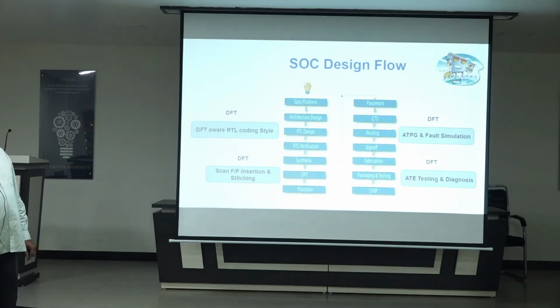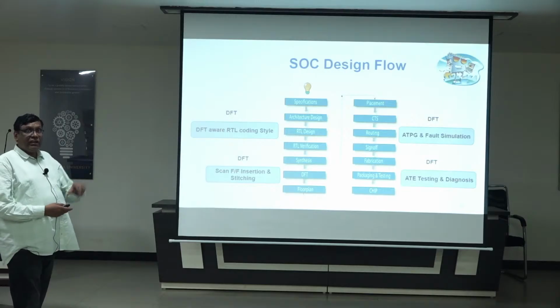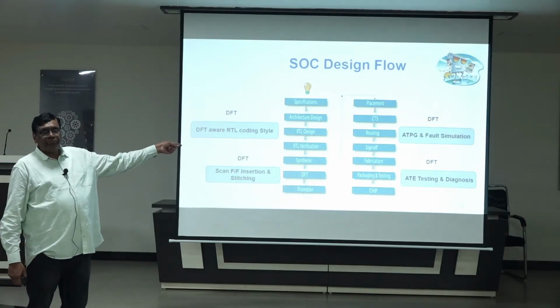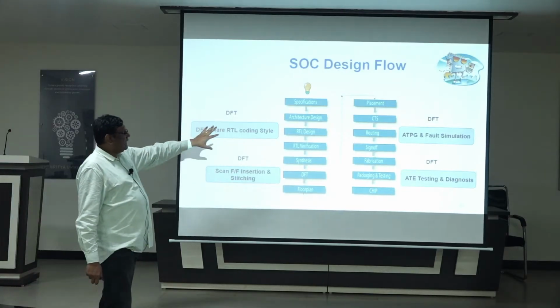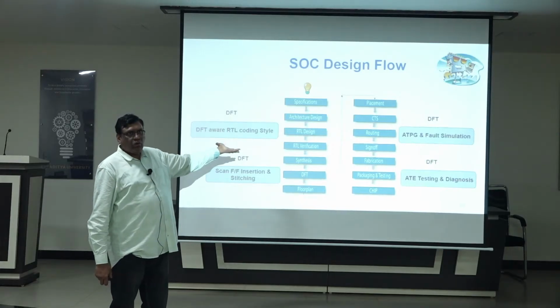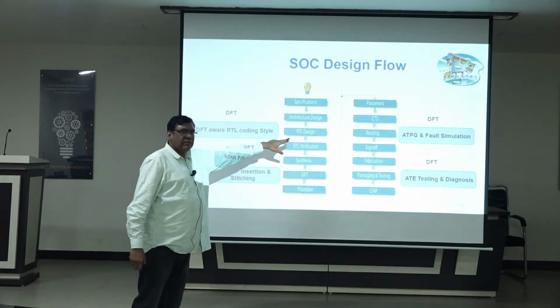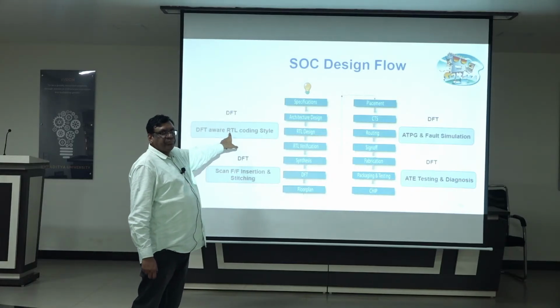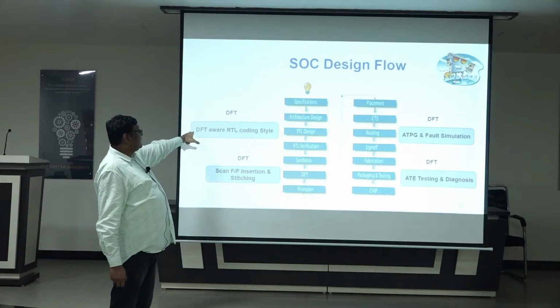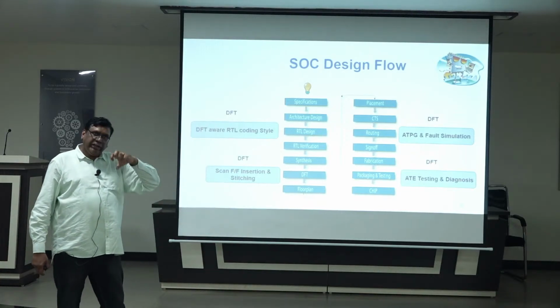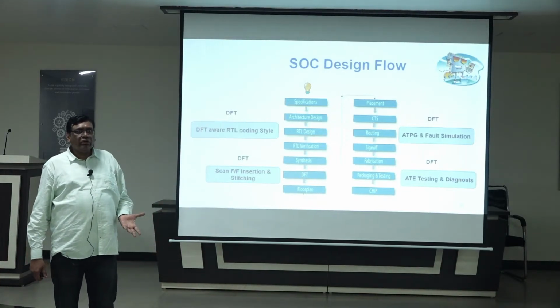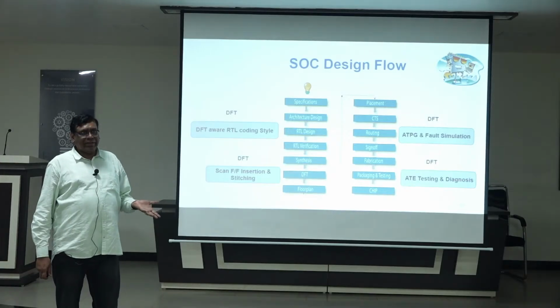Okay, SOC design flow. Initially we have seen the same diagram, but now we see the DFT, and I want to show you where the DFT will be involved in it. Before synthesis, during RTL design itself, we will use the DFT, that is DFT aware RTL code. We will initially write extra DFT code to enable the testability.